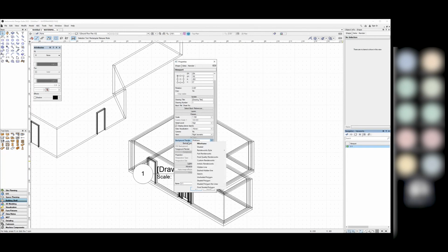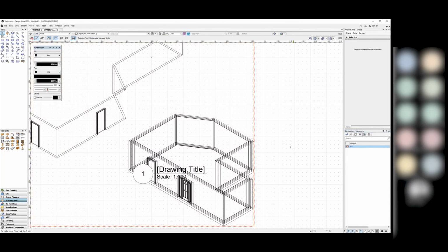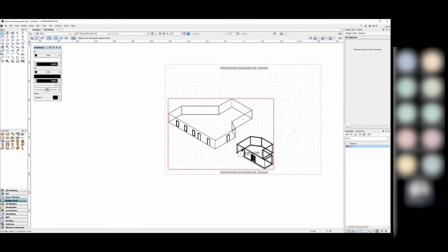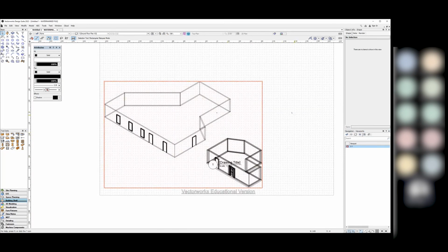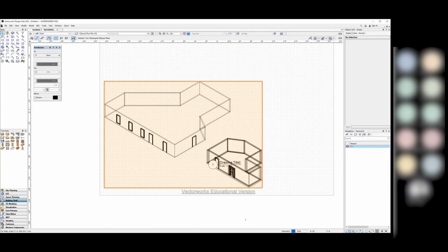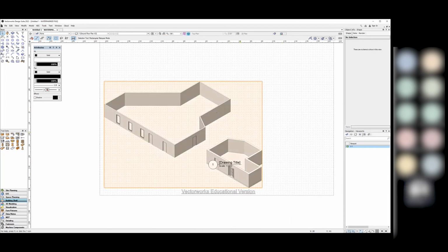So currently the background render is render wireframe; change that to shaded. Yes, this is what I wanted it to do. When you make enough changes, after a while, you won't see the changes taking place. Instead, you see these red diagonal lines appearing around the drawing. This is very common, and you can fix it really easily by right-clicking and choosing Update. And that will now update.